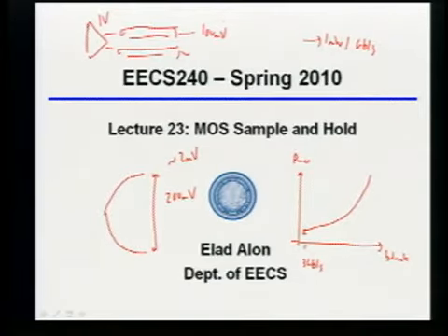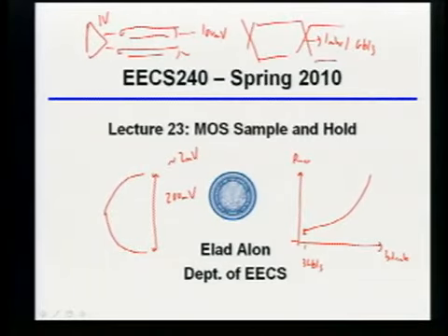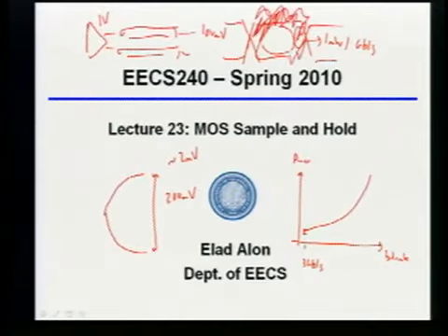In other words, if I look at the eye diagram of your output, I want it to look basically like that. The output of your comparator better have a nice clean eye diagram. If the output of your quote-unquote link looks like this, obviously my drawing's not great, but like that, then that's no good. So no cheating, because you have to actually receive the bit. It needs to be a digital link. That means you have to make a decision about whether it was a 1 or a 0. Other questions?